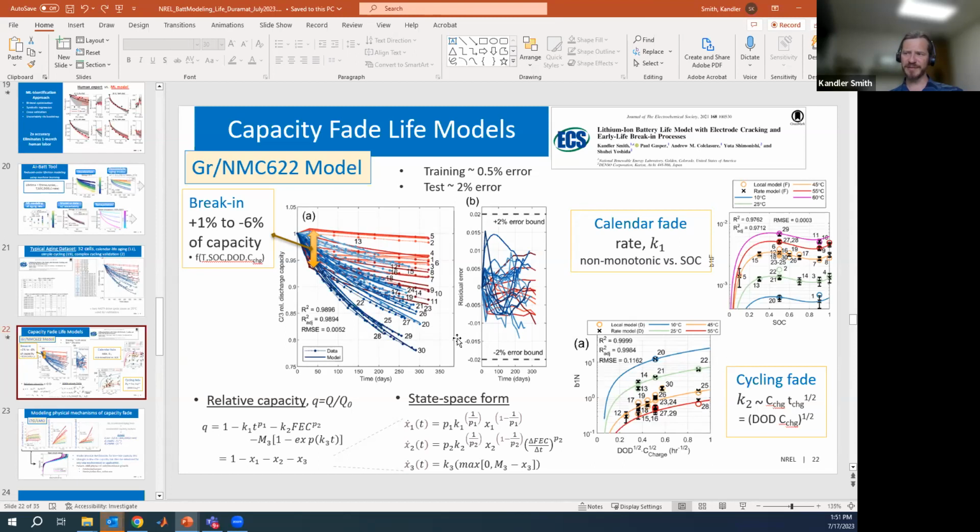Some of them were relatively observable ahead of time and others were not really. Many of them were coupled with resistance growth. So I think tackling not just capacity changes, but resistance and power changes of the cell are important. One of the things, which gets to Andrew's question about metrology tools, is that the electrolyte's changing, and in some cases drying out, or turning into a gas, and the cell is kind of bubbling up, or turning into a balloon.